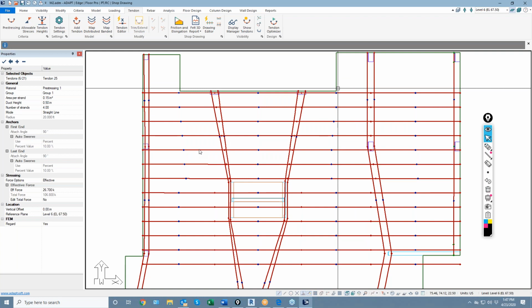Another question, why do you have only 2 strands as distributed tendons? Is it because it's an example? Usually we have about 5 tendons at 5 feet on center. It's really just dependent on the requirement. It's just part of the design. So to start, there are certain code requirements that we have for design of PT slabs. We know we need a minimum amount of pre-compression.